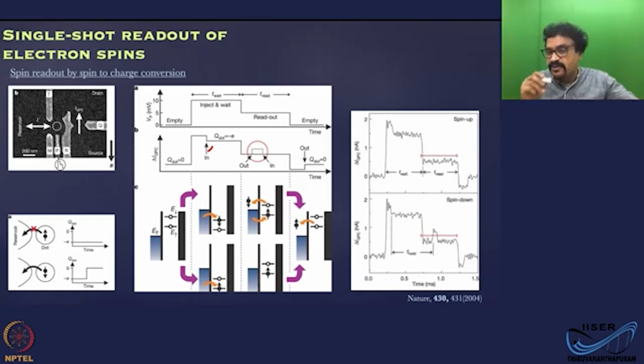The quantum point contact current is also going to respond the same way, because the pulse is an electric field. A voltage pulse is going to create an electric field at the channel of the quantum point contact. That also will reflect the same thing. So this solid line here is a representation of what you would see in the quantum point contact, how the current is going to change. This is a representation. Actual data is here. We will analyze that in a minute.